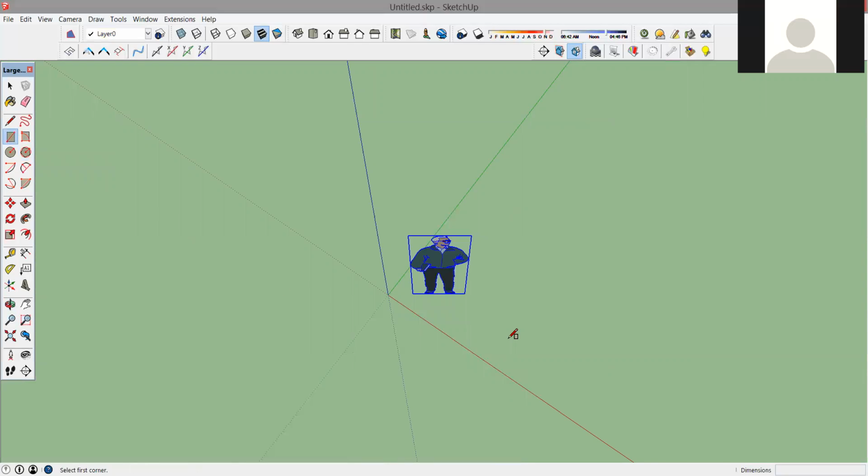I'm going to select anywhere on the screen, it doesn't matter what's here. Notice that in the lower right hand corner, I see dimensions. I see 1 foot 6 and 3/8 by 1 foot 6 and 3/8. The program wants to draw perfect shapes, so it chooses. If you're close to a square, it will give you a square. If you go to a rectangle, it will give you a rectangle. But you can dictate the size of your object by typing on the keyboard.